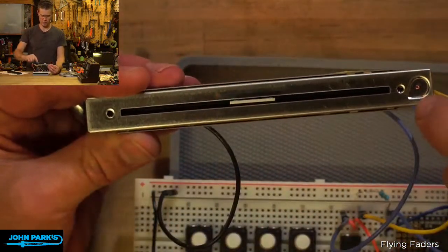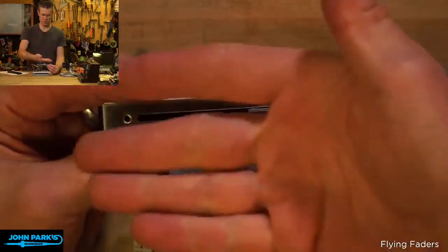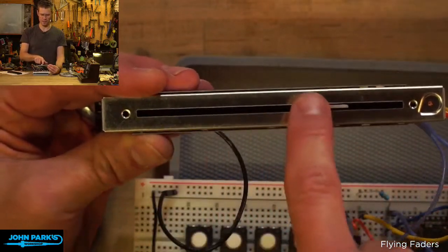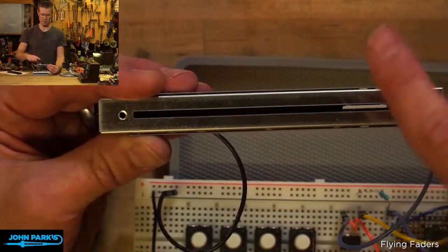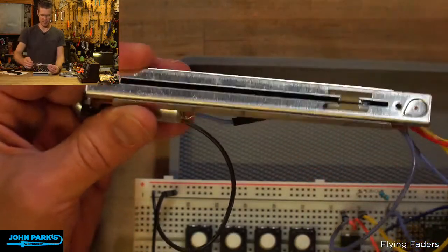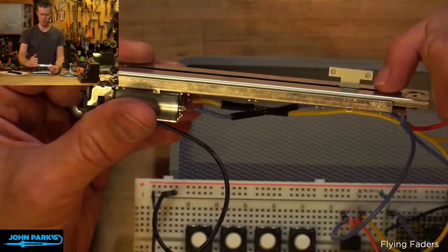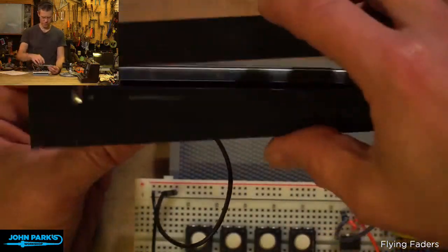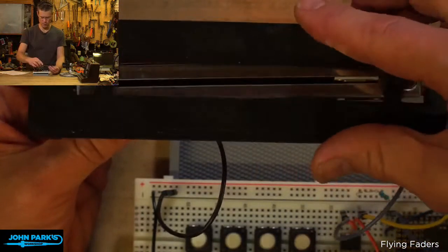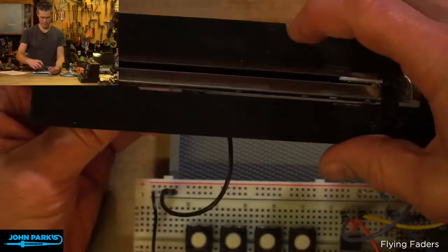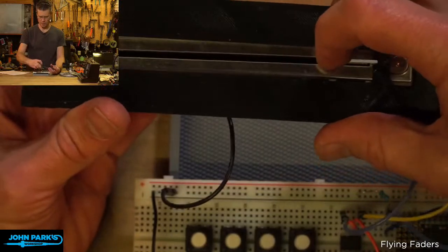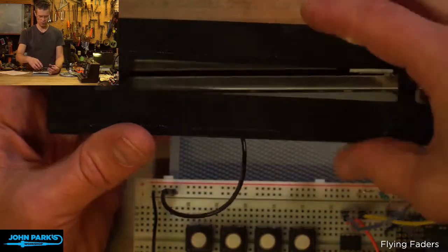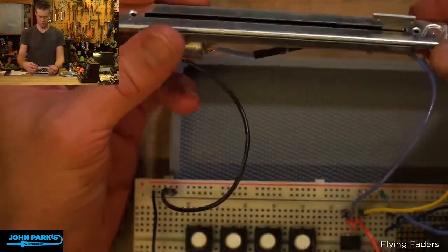And typical for pots, there are a couple screws in the top for mounting. So this is usually, you'll just have a cutout for the track and then a couple of screw holes to mount into a top plate. You can see we've just got, I think it's 4 millimeters of clearance there for material. So I tried to add a little cutout for that right there, so that won't get stuck. We'll see when we try to put that in if that works. That was the first iteration.